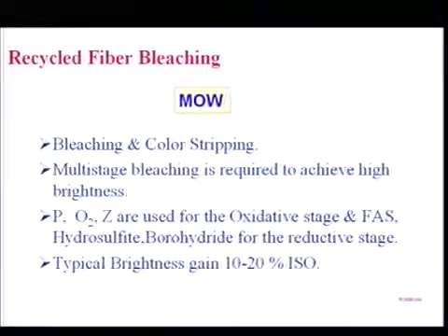Typical brightness gain, you can get as high as 10 to 20 points. It depends upon the amount of dye. If you have only pink color present in the system, you can get as high as 20 points gain in brightness, just removing that dye, making that white bright paper.